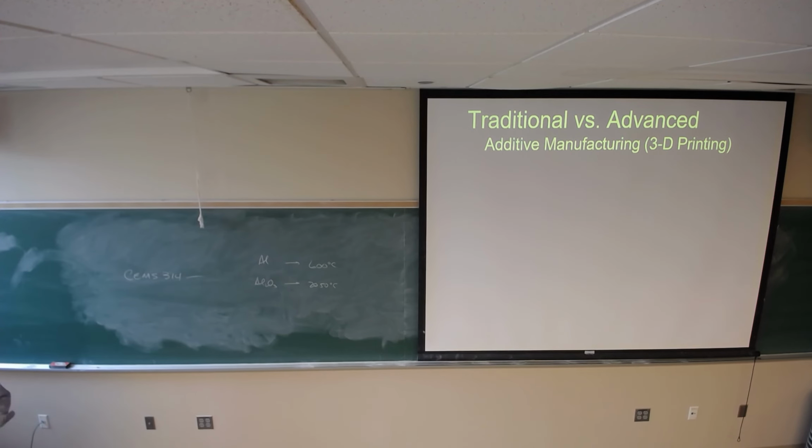There's a problem there too, right? And direct printing, like where you lay down ceramics and sinter it at the same time, and then it cracks and you're surprised because you've ignored all the heat transfer, thermal expansion problems, and the fact that you were working with a brittle material that doesn't do well in absorbing strain, dissipating strain energy. I can go on and try not to. All right.